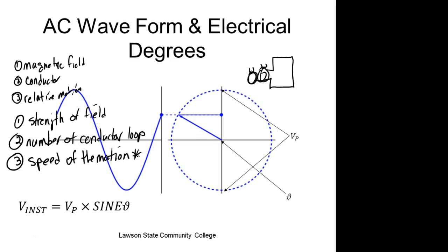Now, if you turn it off and measure it, your battery's going to measure what we call a surface charge, where it's going to measure over 12 volts if you just turn it off. If you set it overnight, it should measure 12 volts, pretty close to 12, because it's 2 volts per cell. It's a 6-cell battery.